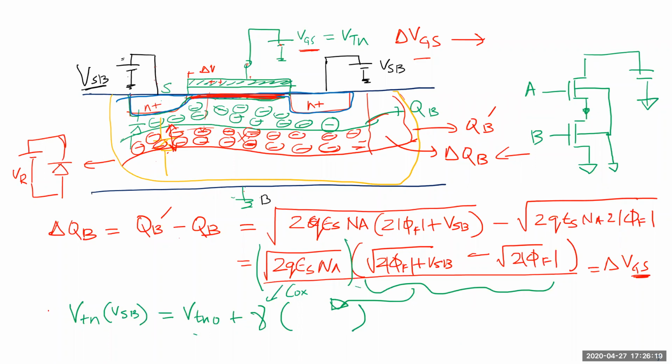So this voltage is at a higher voltage than the ground. Which means that this is ground, 0 volt, but this source is not. So that's your VSB, which means that the VT for this device is greater than VT for this device. Let's say this is VTA, this is VTB. So typically in a CMOS NMOS, your VSB is always a positive quantity, or your source is higher, which means your VT increases.